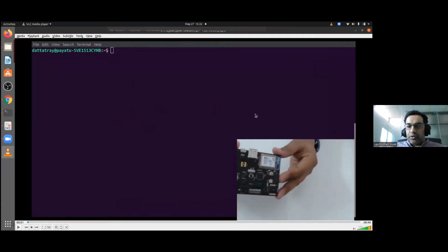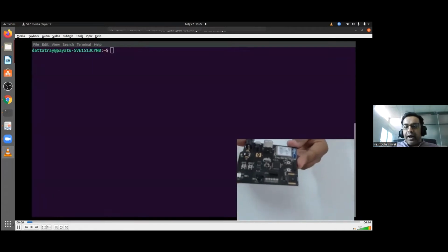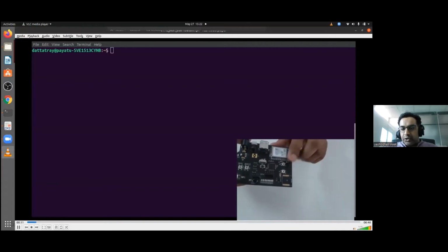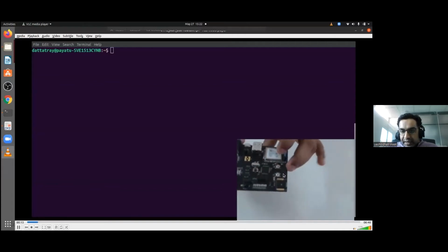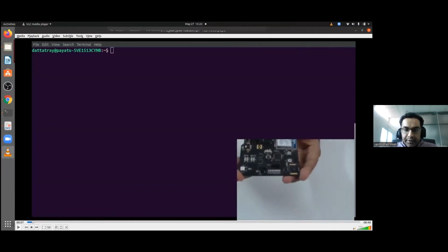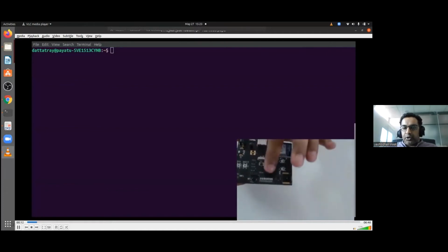Oh, yeah. So this is recorded by my colleague Shakir, right? And I'll explain what is happening. This is our debug board, and we are going to attack this board itself by the JTAG. As you can see, these are the ports at the bottom. Let me just rewind, hold for a moment. Here on the front, we have these dual headers. Out of this, one port is SWD, one is JTAG. So we'll try to scan the JTAG pins with our bus auditor.